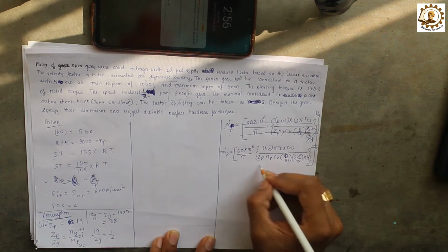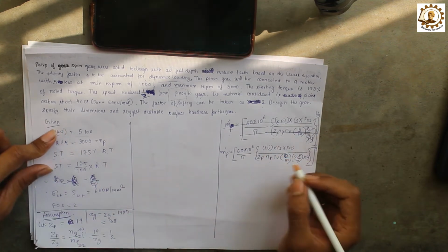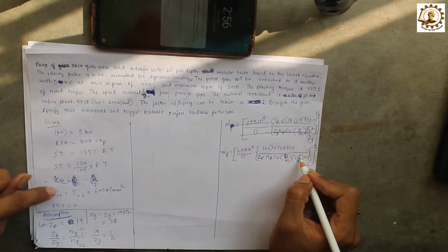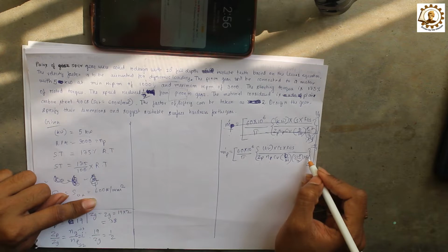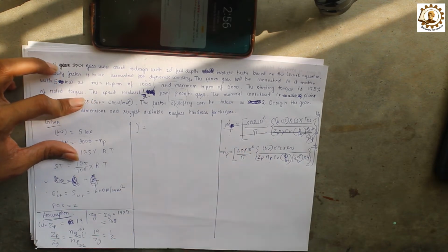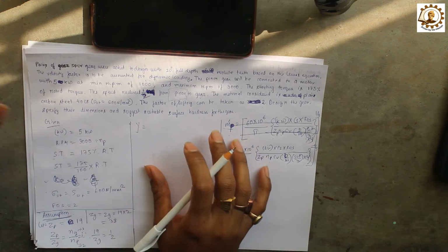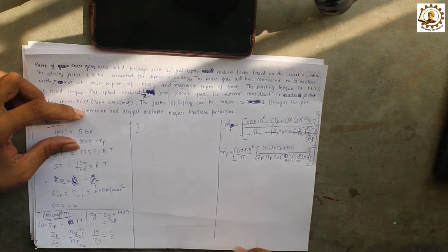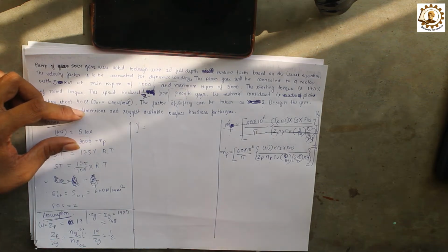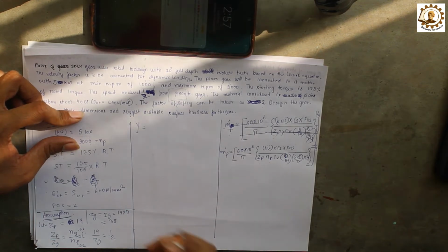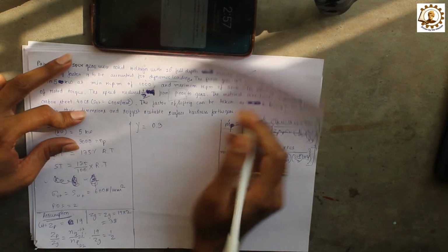I know what is Z_P, I know what is N_P, what is kilowatt, that is power. I know what is the factor of safety, it is given over here. I know what is S_ut, it is given over here. So how to calculate the Y? How much will be the Y? As per the Lewis table, what we have seen in the previous class, for 19 teeth, I'll show you, we will get a Lewis factor of 0.3.